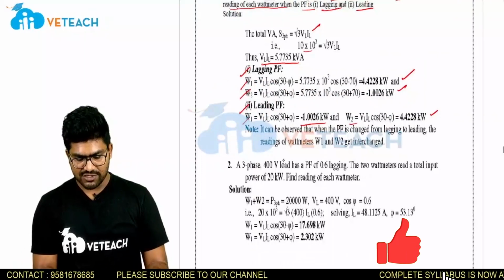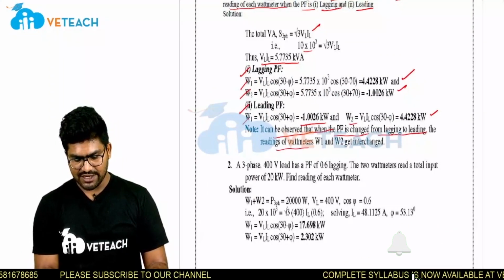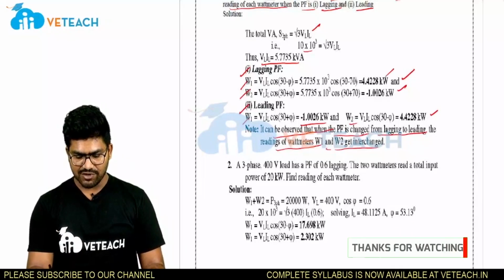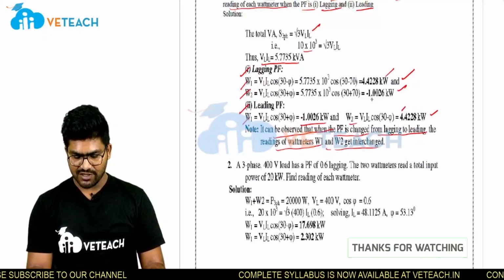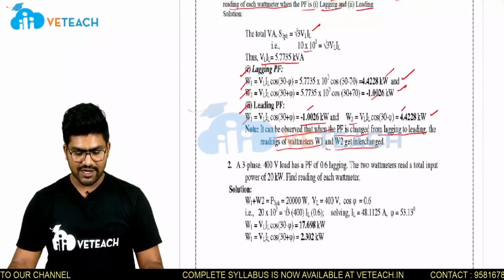So it can be observed that when the power factor is changed from lagging to leading, the readings of wattmeters W1 and W2 get interchanged, right? Here W1 becomes W2, and here W2 becomes W1. So from leading to lagging, the wattmeter readings are changed.